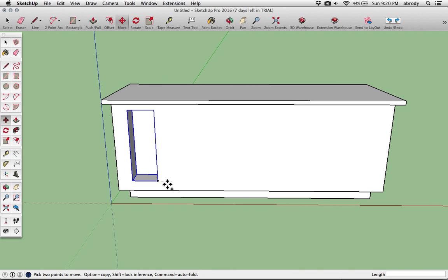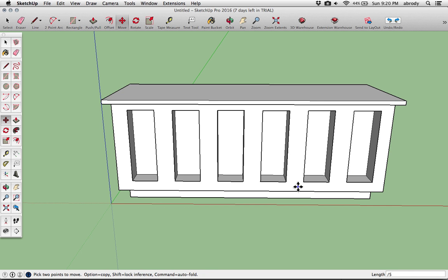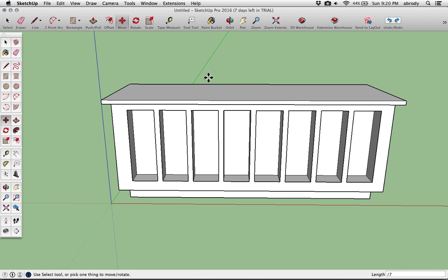What you'll find is now when you copy, and of course, again, this is something we've already touched on, I'm going to use the Move Copy command, copy this puppy over, and then I'll use my modifier. Remember, we talked a little bit about modifiers, all these things that are sort of alterations to the command. And one that we have that's really nice is the array modifier. And all I have to do in this case is type in slash and some number, say 5. And I can make 5 copies that span in between the original and that first copy. Now I think I want more, so I'm going to type /7. Yeah, that looks a little nicer.